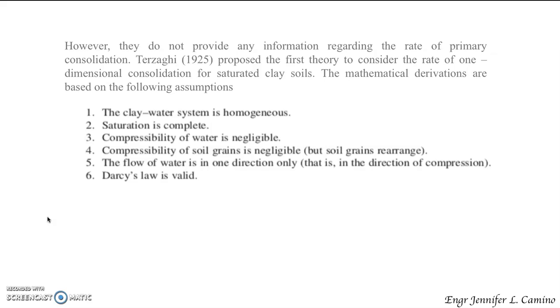According to Terzaghi, he proposed the first theory to consider the rate of one-dimensional consolidation for saturated clay soil. The mathematical derivations are based on the following assumptions. The clay-water system is homogeneous, of course. Since this is one-dimensional, saturation is complete, compressibility of water is negligible, compressibility of soil grains is negligible, and the flow of water is in one direction only, that is the direction of compression, and Darcy's law is valid.